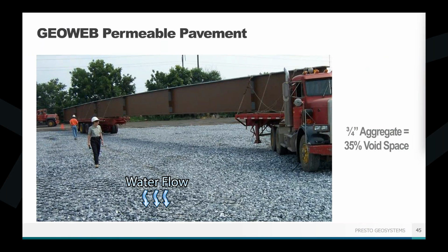I know that there are some sort of outdated regulations out there that say aggregate can't be porous pavement. We've heard some weird stories, I'll say it like that, where people are claiming that putting in a stone parking lot or something doesn't count as a permeable area. And so we are able to help you give those supporting calculations, meet those regulation needs, make sure everybody feels comfortable, that sort of thing.